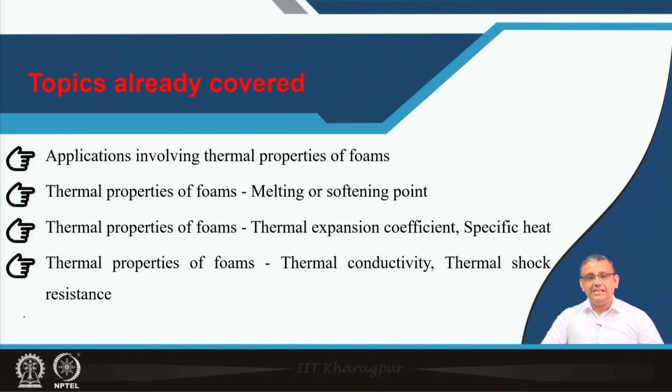We learned that thermal shock resistance depends upon many factors and also some mechanical properties like the Young's modulus and Poisson's ratio, which actually control it. For thermal shock resistance of ceramic materials, we learned that the material should have a low expansion coefficient and a low modulus, and also a high fracture toughness to have sufficient thermal shock resistance.